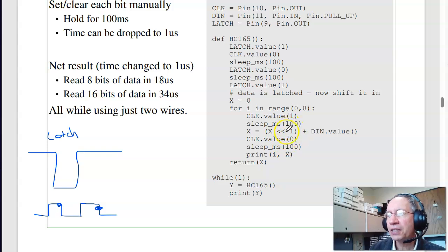What the shift does is I'll read in the first data point, get shifted again, shift 8 times. So this assumes the most significant bit comes in first, and the last one I read will be the least significant bit. And you can do it either way. When I read in the data, I can either read it in by shifting left or shifting right. If I shift left, the first bit is the most significant bit. Shift right, the last bit is the most significant bit. You kind of have to know which one you're doing, which one you want. It can be read either way.